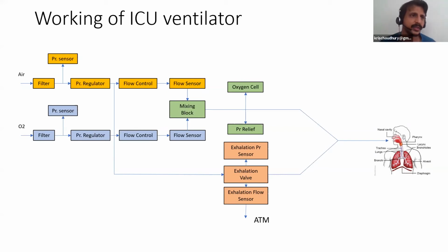This is a mechanically set valve, which you cannot set. This is preset by the manufacturer and left. It is there always to ensure that if there's any problem in the whole ventilator, and if any of the electronics fail, you should never have more pressure getting into the patient's lung, which would lead to a lot of lung damage and even death.